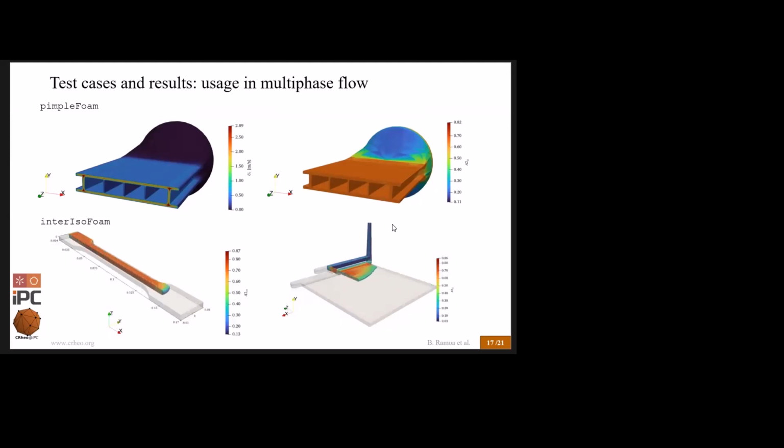And we have also made this for multiphase flows, because I will use this for injection molding. I need this to work with multiphase flow, and this is the test case of an isothermal filling where you have a dog bone specimen. And I don't know if you will see it here, but you'll be able to appreciate it in the convergence region here. You'll have an increase of orientation, and in the divergence region, you'll have a decrease in orientation.